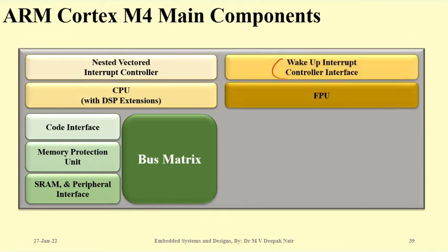Then we have wake up interrupt. That means whenever, for example, your system is in deep sleep, you can wake up the system by sending an interrupt. There is a particular unit which is always awake for interrupts. That means even in deep sleep mode, it will be ready to accept an interrupt, and you can wake up the system through an external interrupt or timer based interrupt also. So there is a separate unit for that: the wake up interrupt control interface.